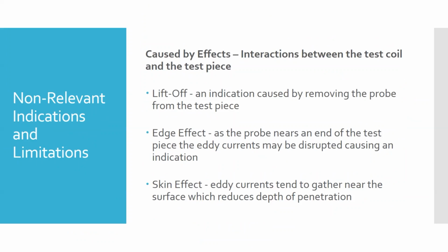So those more sophisticated probes and testers can overcome some of those effects. Or with a simpler tester like we have, if you're looking for both front side cracks and back side corrosion, you may have to set it up for those surface cracks and use a small surface probe. And then if you're also concerned about corrosion in a lap splice or something, you may have to reset everything on your tester, use a larger, lower frequency probe and go back over the same area, right? So you can do it, it just takes longer, more effort.